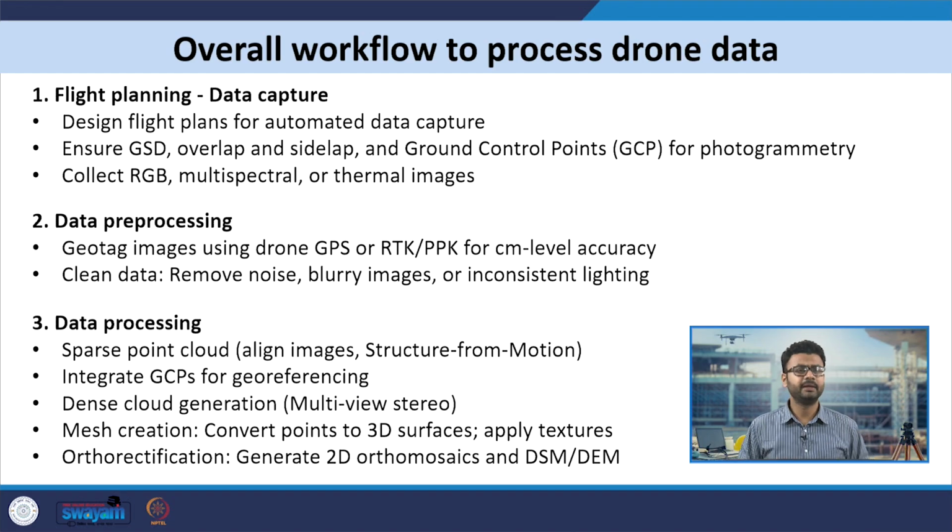In the flight planning stage, we design the flight plans for automated data capture, and in this process we ensure that we have sufficient ground sampling distance, sufficient overlap and side lap, and good coverage of ground control points for photogrammetry. Then, based on the flight planning, RGB, multispectral or thermal images can be collected.